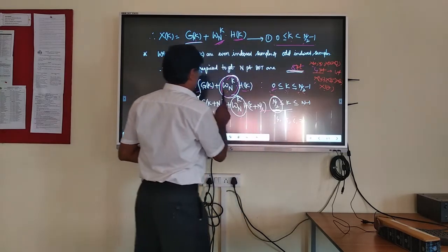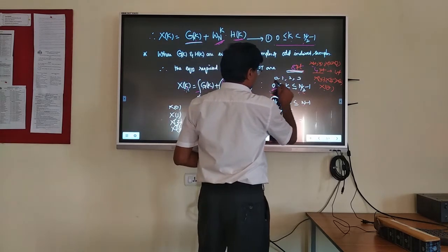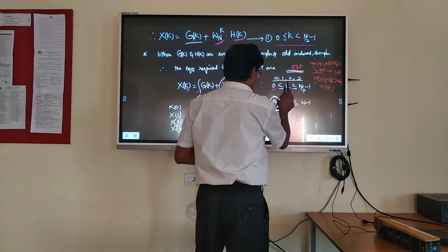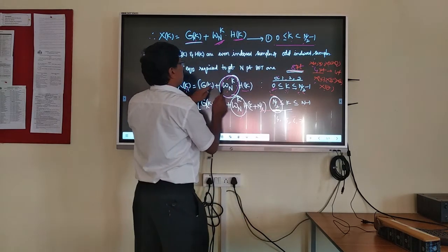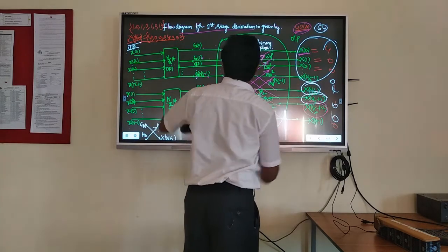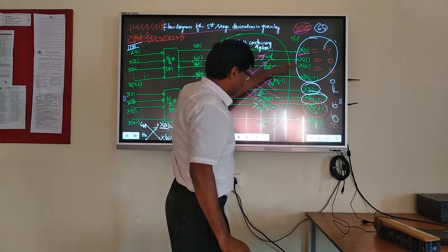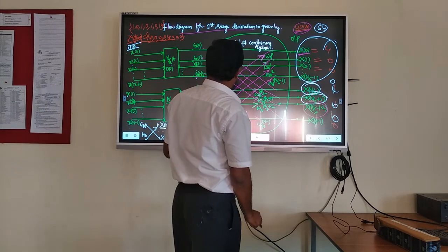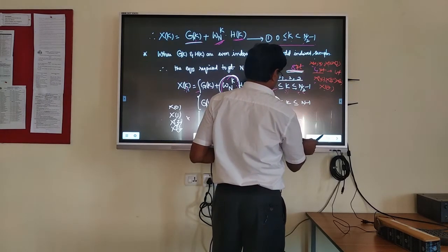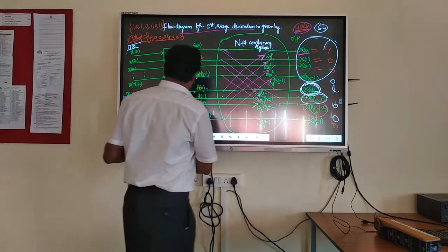See now, for example, k is 1. Here k goes 0, 1, 2, 3, since N is 8 points, so in the first half you get these. X1 is equal to G1 plus omega N power 1 into H1. That's how we get it. Similarly, you get everything. For example, here the half point, X of N/2.